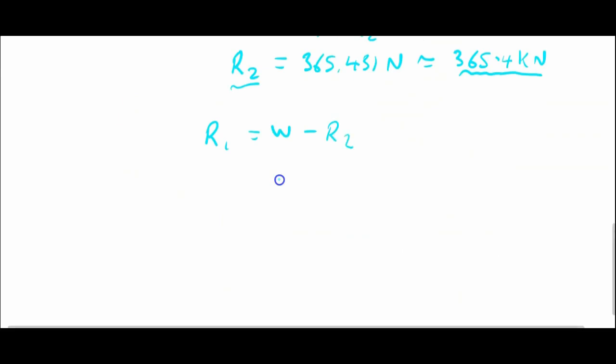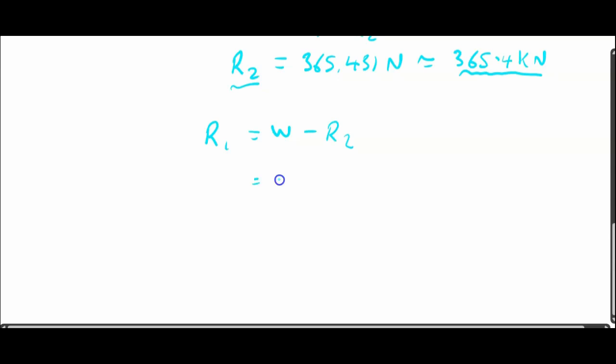And we know what the weight is. It's our mg, isn't it? So this is mg here. So weight mg, so 40,000 times 9.81, and minus this value that we've just worked out previously. Okay, and if you do that, I did it earlier on, save me typing it into the calculator again, and that will come out as approximately 27.4